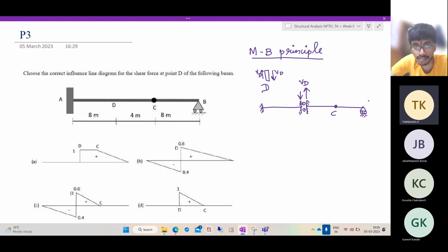This is the point C, this is the point B, this is the point A. When we apply this force, you see here it's a cantilever beam. You should be very careful. It doesn't mean this beam will bend in this way. No, that's not correct. Why? It's a relative force, a relative slip between the two sides of the small beam section, that we are applying. So we are not applying a displacement, we are applying a shear force.